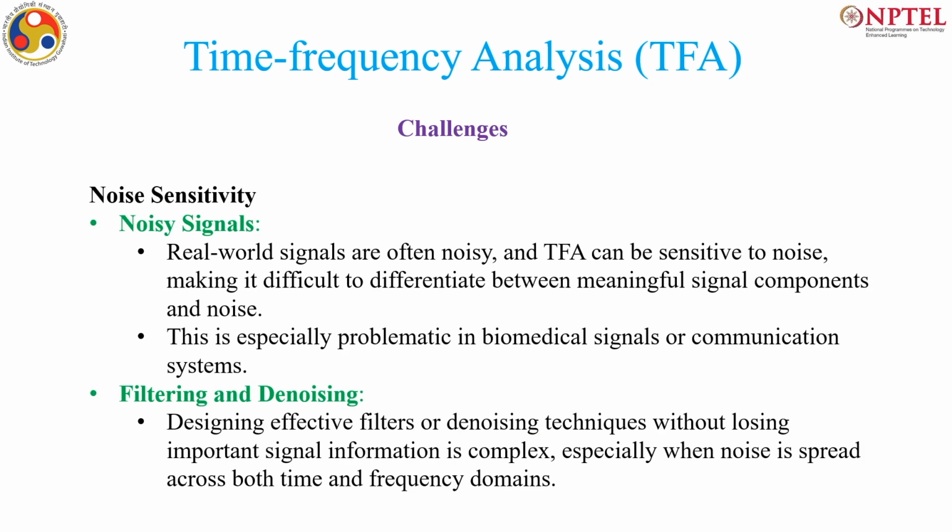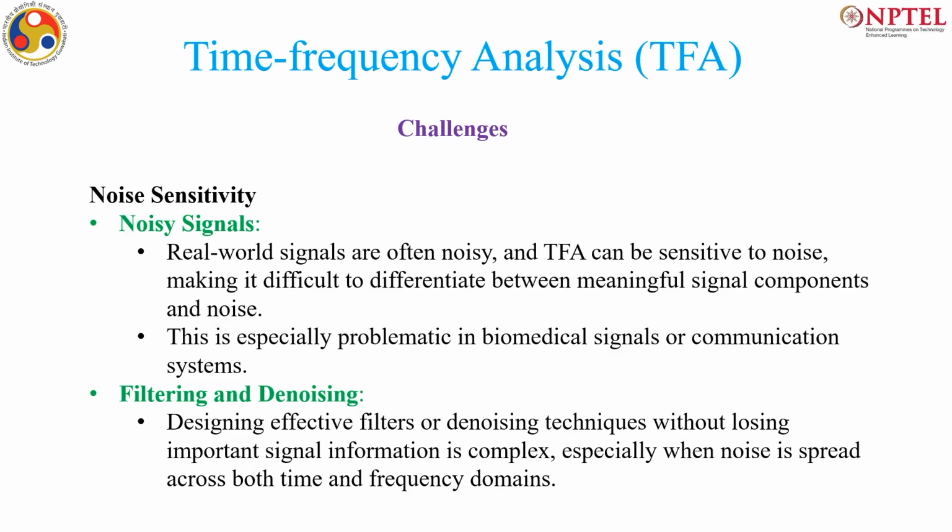Also noise. Now, noise is already a challenge, be it time domain or frequency domain analysis. And in time frequency, because you are taking windowed segments, you sometimes may not be sure whether a specific pattern is because of noise or because of a signal component, and that makes filtering and denoising extremely difficult and complex.